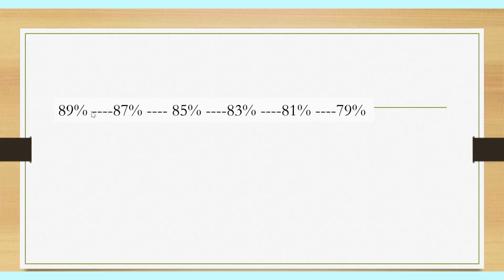So now let's see what the reduction means. Here is our actual takeoff weight torque, which you worked out. Then we start pushing the RDC TOP switch on the engine panel of the Dash 8. Every push, if you recall from your AOM, gives you a 2% reduction in the torque. So every time you push, you're reducing by 2.